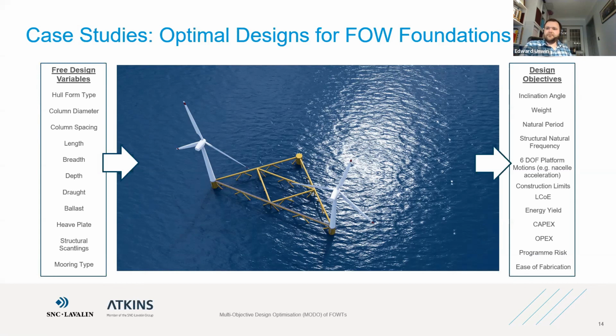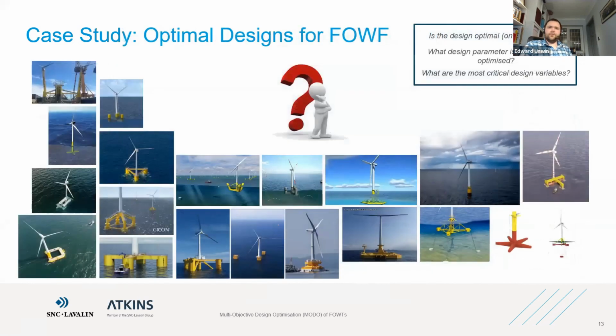Okay, great. I'll go to the final question from James Hamilton, who says, floating structures often yaw at the slow drift period. Is this an issue for the turbines? Not so much. Not at the slow drift period. If we're up in the 1 or 2 minute type area, the controllers and the yaw motors can respond relatively well to that sort of period of motion.